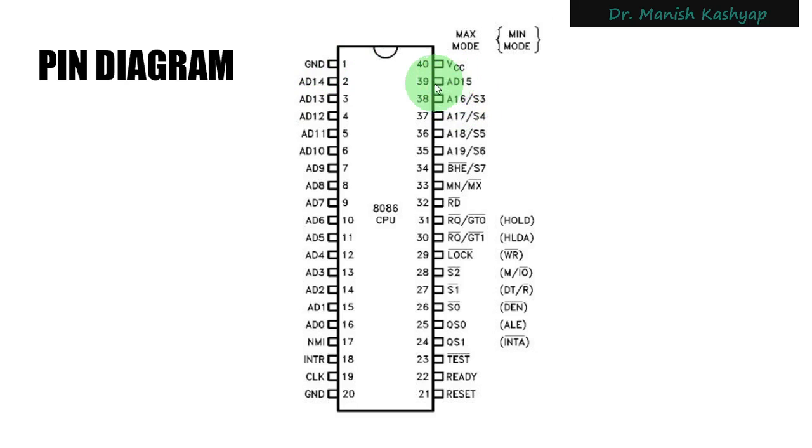So these have to be internally connected through some resistance, which will let you know that this point has a potential of plus 5 volts. But there are multiple pins in this integrated circuit, so this ground, which is supposed to be 0 ideally, does not remain 0. It also acquires some voltage because of multiple pins being grounded to the same pin. That is why, to keep the ground voltage at 0 absolutely, we have these two pins here.